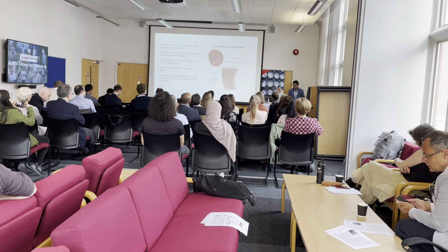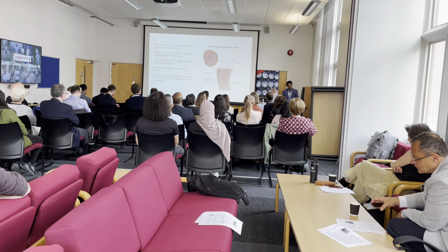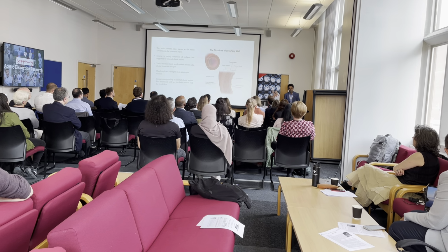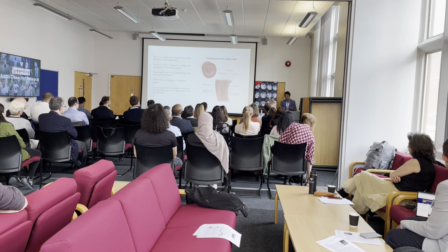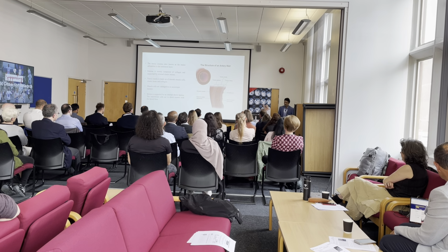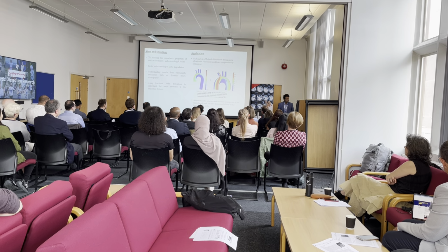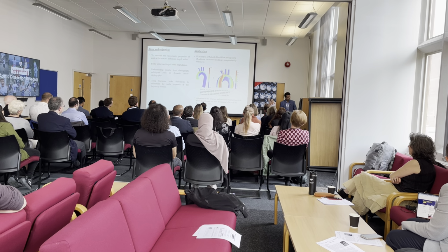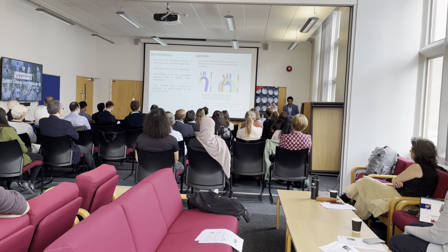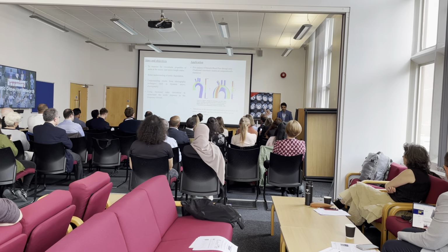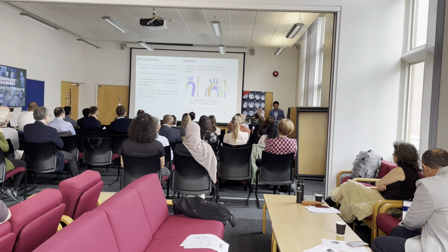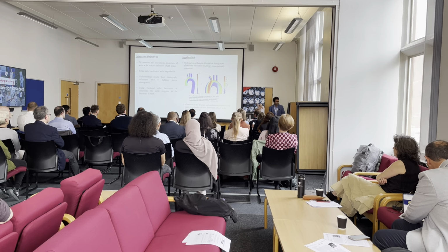Now, most of the nano indentation tests which we performed were on tunica media, because tunica media comprises muscle cells which have mechanical properties changing across the X, Y, and Z direction, which also implies that they have anisotropy. The aims and objectives of this research were to measure the viscoelastic properties, because we needed to understand how exactly the mechanical properties change in the frequency domain, and how the stiffness values change as we go from the macro length scale to the micro length scale.